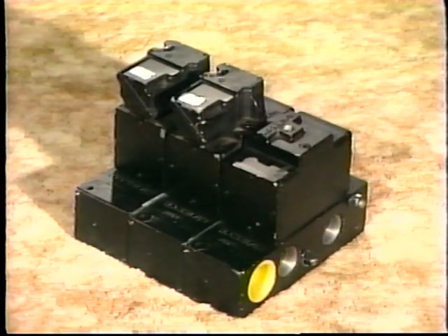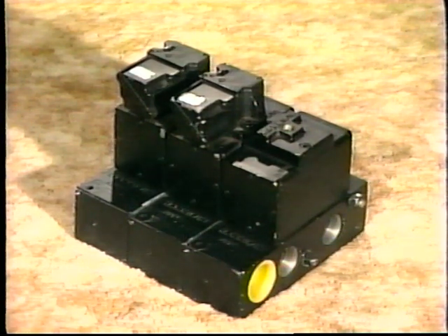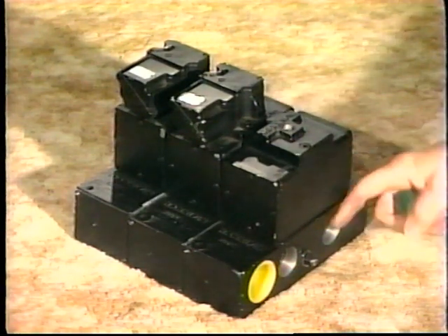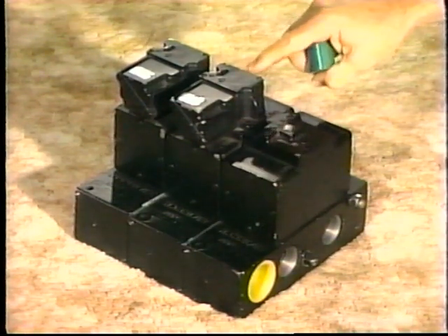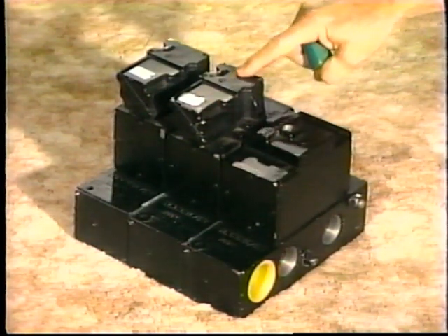Pilot actuated valves may be internally or externally piloted. If the pilot pressure comes from a source within the valve, it is said to be internally piloted. If the pilot air comes from a separate source, it is said to be externally piloted. As you might suspect, the larger the valve, the greater will be the force necessary to shift the spool. So while the solenoid you see here couldn't develop enough force to shift the spool of this valve, we can shift the spool by using the pilot operation like we just discussed.